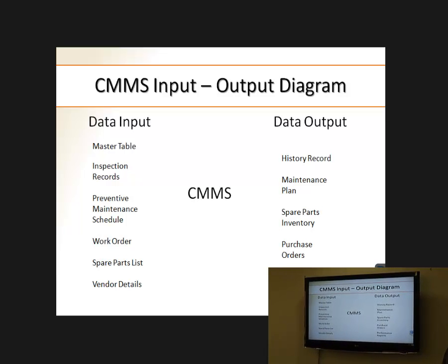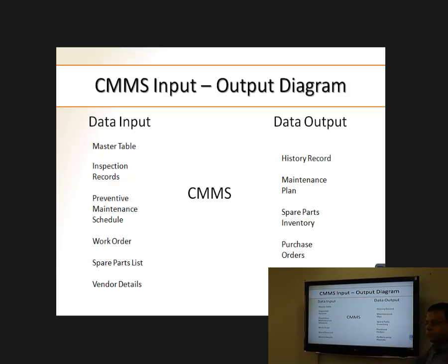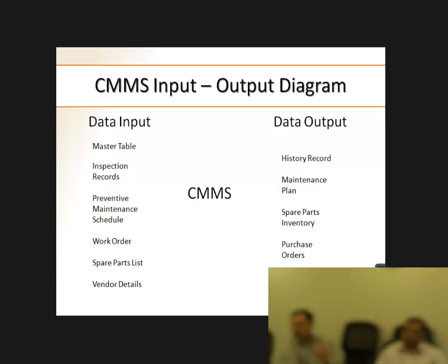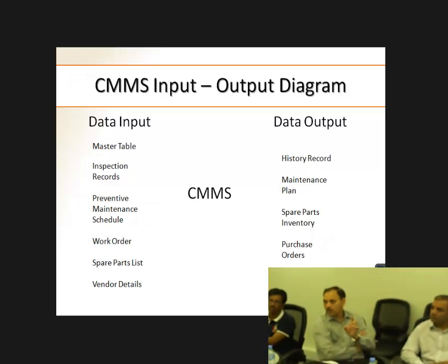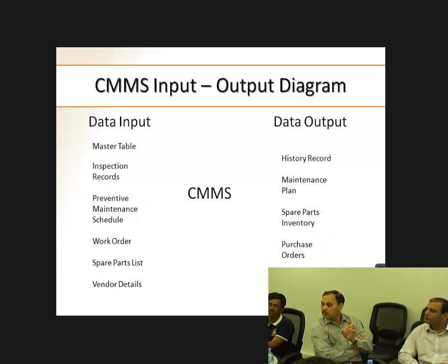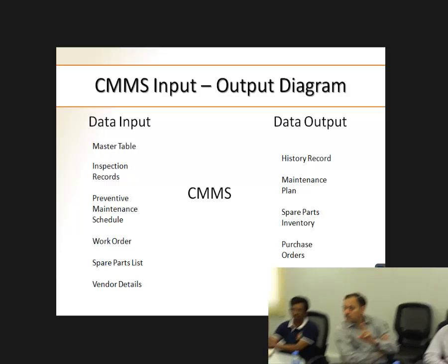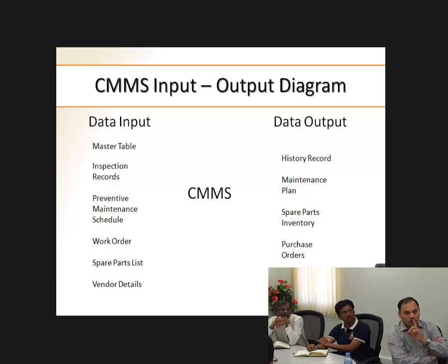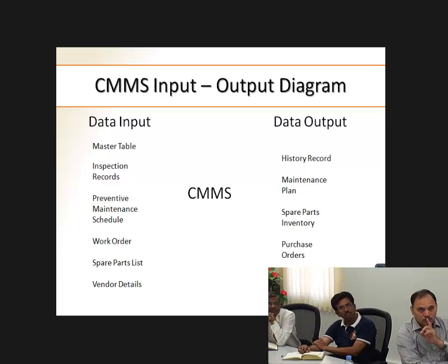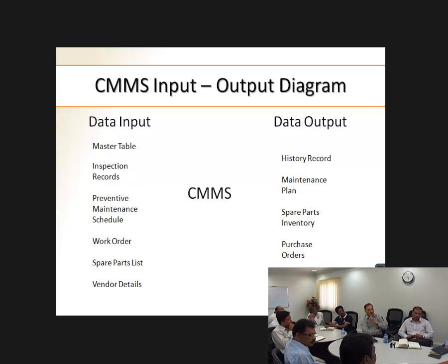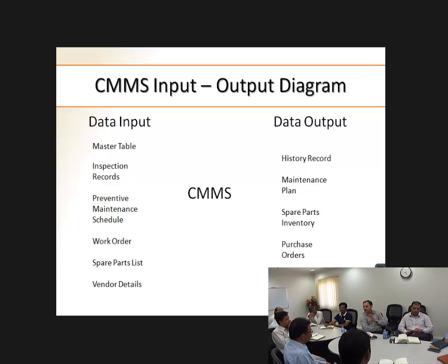And the maintenance plan, are you planning to generate it on a weekly basis? Weekly or hour by hour, because some equipment is hour based and some monthly. For example, for the compressor, at 3,000 hours we have to replace that. It will come. So it depends on the equipment. For vehicles, it depends on the number of kilometers. For IT equipment, it depends on the type of equipment.